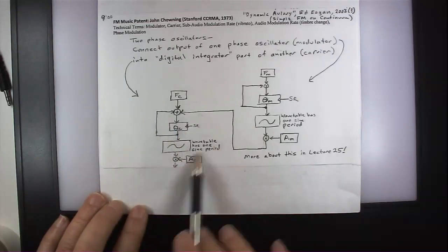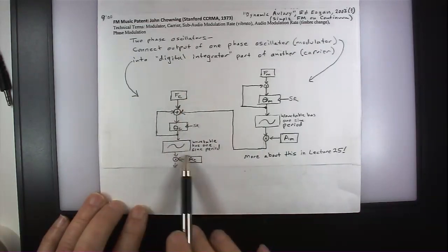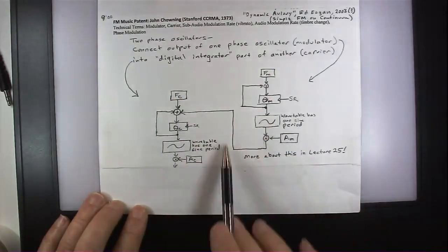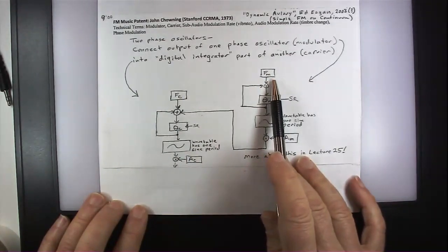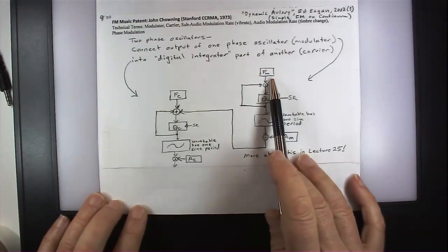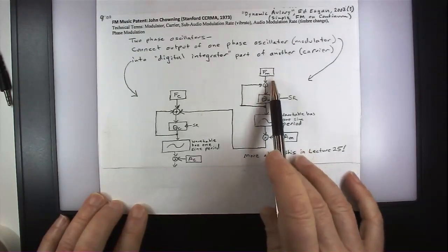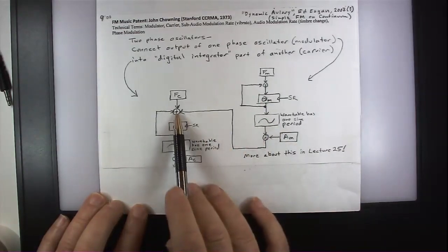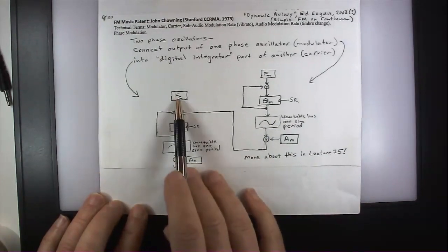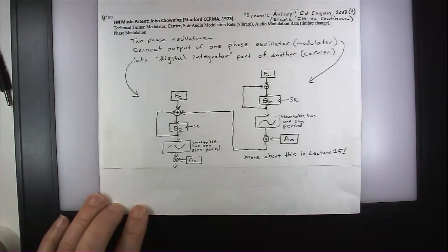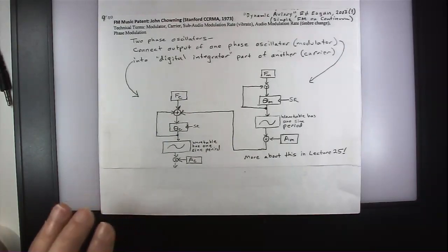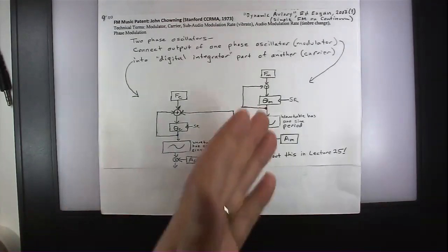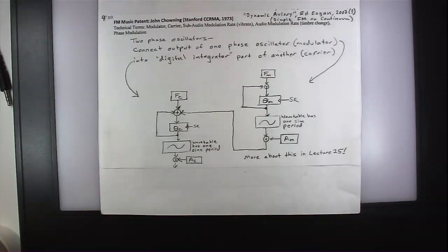So what happens here, you've got this guy here, and normally FC determines the frequency. So this is some sine wave playing at that frequency. Well, now you add this in. Let's say FM has a really small value, like a quarter hertz. Really, really small. 10 millihertz or something. And so this is going through really slowly. And it's got some amplitude of the modulation here. What is this doing? Well, sometimes it's adding a positive offset to whatever your frequency is, and it's adding a negative offset to whatever your frequency is. So your frequency is just wobbling over time. It makes a sort of vibrato, right? It makes a low frequency oscillator modulating that. You hear your frequency go up and down and make some sort of vibrato-like sound, sinusoidal vibrato. It may not sound very human, but it sounds like something.